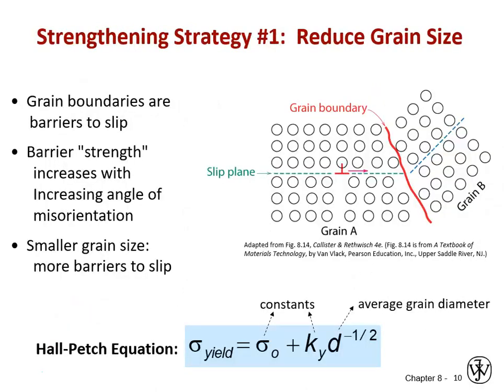Okay, so by now we've covered how dislocations move, and what direction they want to move in first. Hopefully we've emphasized the fact that if we want to deform a crystalline material, the only way to do so without fracturing it is to move dislocations. Hopefully it's obvious now that if we want a material to not yield at a given stress, or we want to increase the stress before it yields, all we have to do is stop the dislocations from moving. So how do we do that?